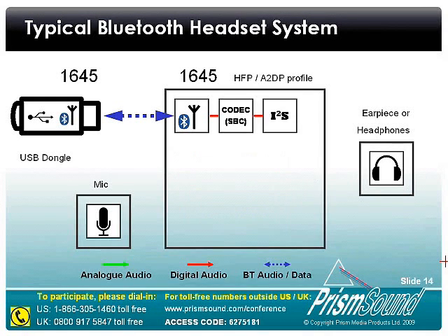After the codec, we typically have some form of digital interface to move digital audio around the board between various different areas of processing functionality. And I've illustrated that with the abbreviation I2S, which is the abbreviation for inter-IC sound, which is a commonly used format for routing digital audio between devices at board level.